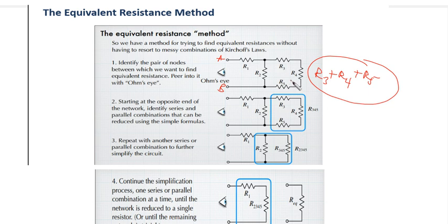If it is parallel that is encountered first, you deal with the parallel. All right. So you are now left with this series combination result and this one now. So you continue the resolution again. You still keep looking from the other end. In this case now, whatever you have here is in parallel with this. So you now use the parallel formula to combine this. By the time you use the parallel formula, you will end up with a single resistor again.